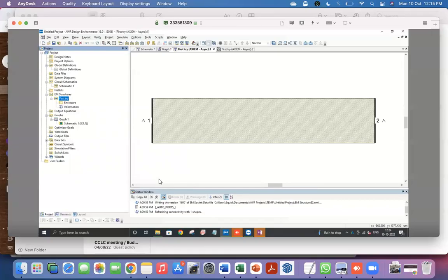Okay. So it's like if you already knew that you expect the response to be something smooth, which means that the S parameters are changing in a smooth fashion as you go from one frequency to another, versus the solver itself trying to see is it smooth, and in which case it doesn't need to even solve all the points you have specified, and it will just create an interpolated curve by itself. Okay, now this can terribly go wrong if your structure has some very sharp features and it's not able to catch it. So this has to be used judiciously depending on what you're trying to do.